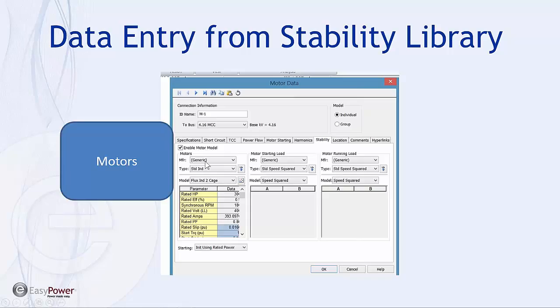There's a generic listing for different sizes of motors, and a couple of library elements that include specific manufacturers. And if you still need more accurate information and you have access to the torque charts for the motor, you can actually digitize these and include them in the model.